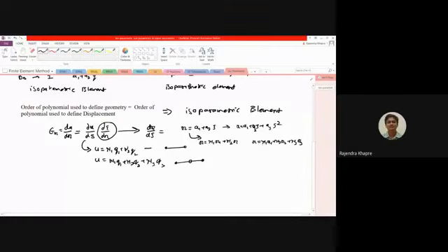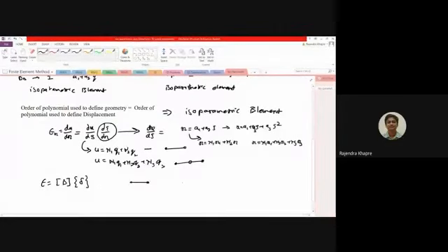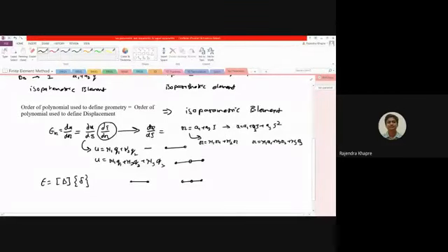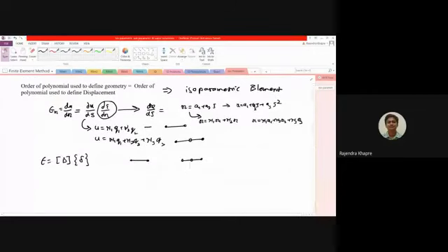So depending on whether you are using a 2-noded bar element or a 3-noded bar element, we have to choose the appropriate equation, and once this is known, you have to get the value of this strain, that is epsilon x. So epsilon x in general can be written as the B matrix multiplied by your delta matrix, okay. So we have already seen this strain displacement matrix for the 2-noded bar element, and in yesterday's class we have seen this for the 3-noded bar element, okay. So I'm not going to repeat this. I hope this is clear to everybody. Are there any queries?